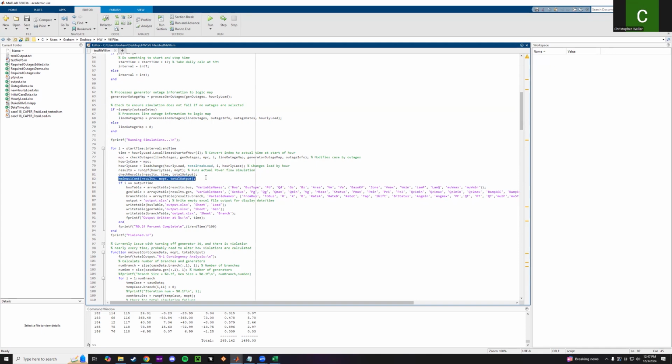N-1 contingency works, but there are a few errors in the current iteration. For example, transmission lines that go down can sometimes create islands. Islands are simply buses that are isolated when a line goes down. This doesn't have any special considerations in the current iteration.